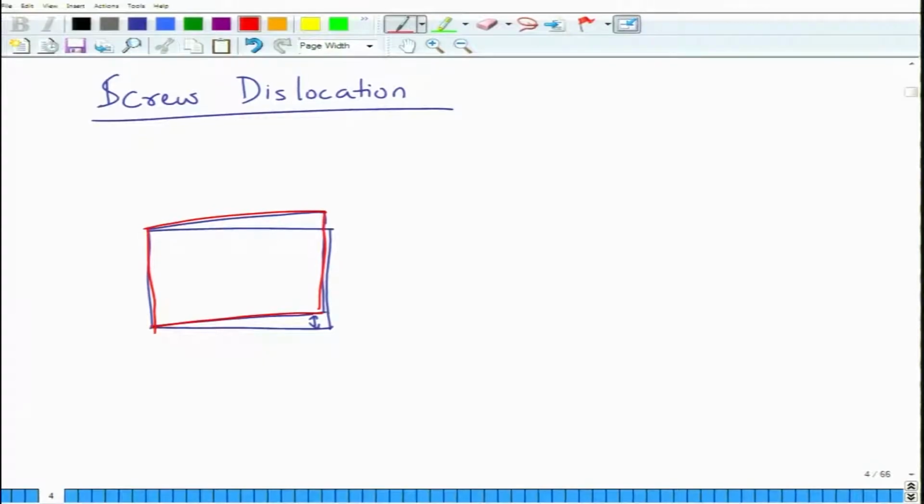and the top part has sheared with respect to the bottom part by an amount equal to the Burgers vector, and this is the dislocation line, in this case T, whereas the other part of the crystal is like this. This is the remaining part of the crystal. Okay. So half of the crystal has sheared. So when you apply stress, in this case the stress is applied in this direction, this is the stress. So the stress, the T vector and the B vector, all of them are parallel.